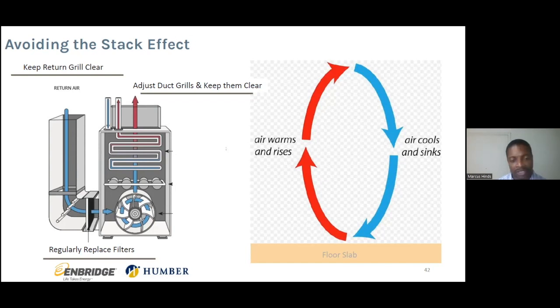So that filter is going to get dusty much more quickly. And as that dust builds, it's going to be harder and harder to force the air through it, right? And then on top of that, you're going to have to replace it pretty often as well, right? So you don't want your filter spec to be too fine, but you still want it to be to a point where you're creating healthy indoor air quality. So this kind of comes with a little bit of a balance.